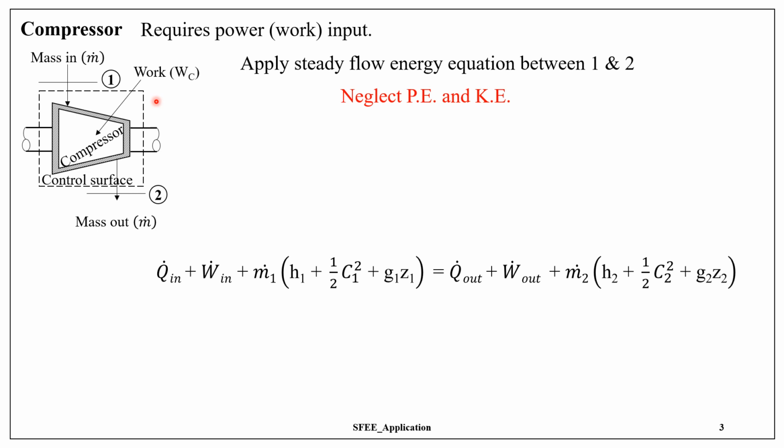Once again, neglect potential and kinetic energies. So these two terms will go off on both sides of the equation. Compressor doesn't deliver work. It requires work from us. Therefore, work out can be neglected. Again, the compressor is perfectly insulated.